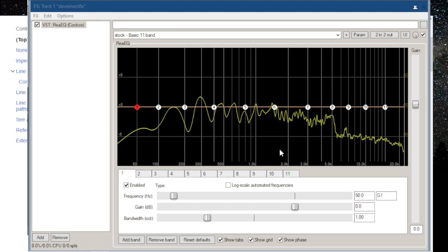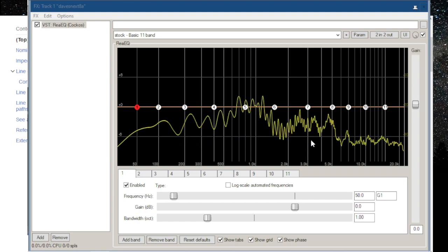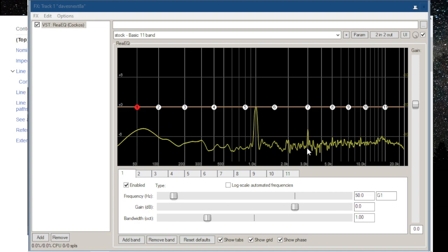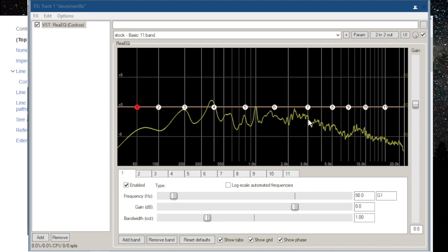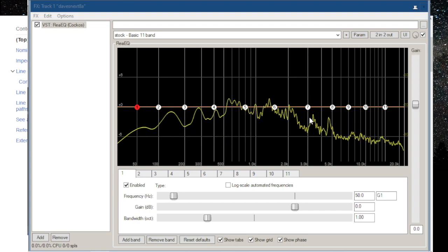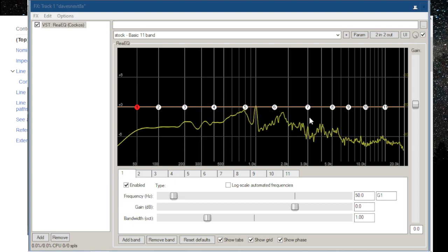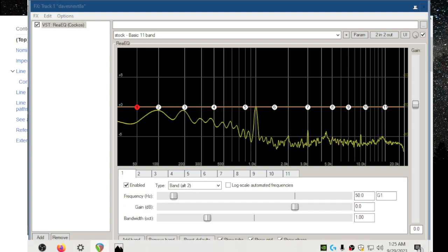So basically, what I'm doing is I'm calibrating. The bottom oscillator looks like it's working a little better since it's warmed up. There's an equalizer where a lot of my stuff from the outside, like the guitar, the piano, and all that other stuff, it's not flat. So I'm going to set it to flat, and we'll run the same test again from 1 kilohertz.